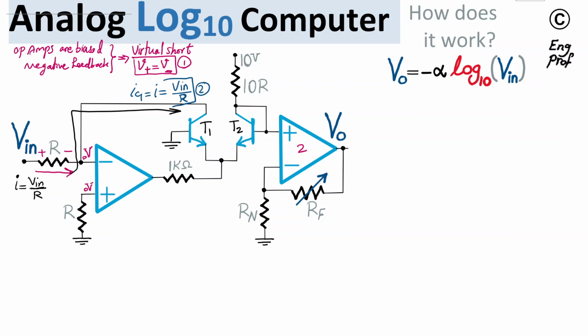Okay, so the other thing I can compute is the current that is going this way from the reference voltage Vref, 10 volt, which is important, through the 10R resistor. By the way, the values of these resistors can be set practically like 10 kilo ohm for this resistor, 10 kilo ohm for this one, naturally 10 times that, 100 kilo ohm for this resistor, and I'm going to talk about the value of these two resistors as well.